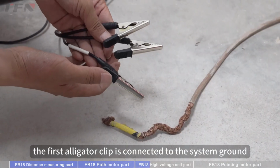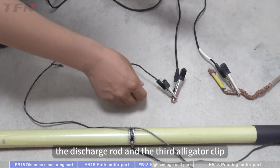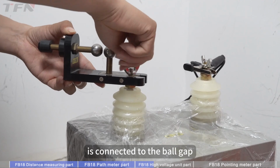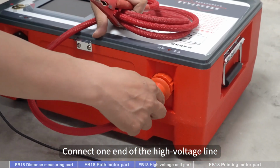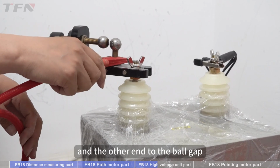The first alligator clip is connected to the system ground. The second alligator clip is connected to the discharge rod, and the third alligator clip is connected to one of the fault phases of the cable. The other end of the capacitor is connected to the ball gap, and it is used at the high voltage end after connecting the ball gap. Connect one end of the high voltage line to the output port of the high voltage equipment and the other end to the ball gap.